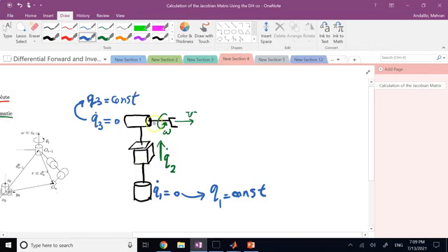What's the effect of that on the angular velocity of the end effector? And you would say nothing. If I lock these two rotary joints and just go up and down, is the end effector going to rotate? Do I gain any angular velocity by just going up and down? Of course not. So the contribution of omega with respect to this Q2 is simply 0.